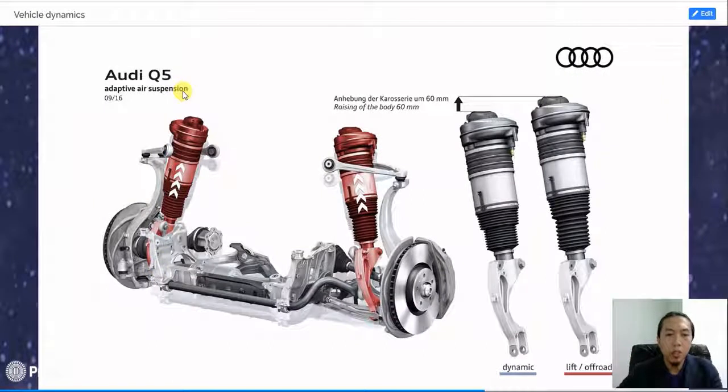In an active suspension system, an actuator such as a linear motor, hydraulic cylinder, etc. is placed parallel to the suspension system, between the wheel and the vehicle body. The actuator uses the suspension space while pulling down or pushing up the vehicle body in order to suppress its vibration due to road irregularities, or road disturbance.